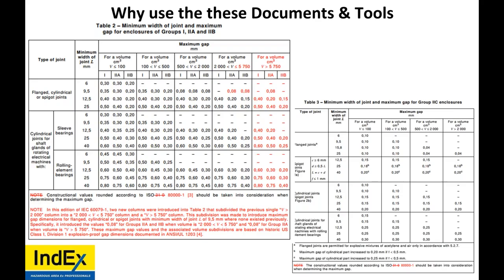If the equipment has an IECEx number for normal Ex, but also has a UL listing for its AEx, NEC 505 considerations, then yes, that can be used everywhere in the world, but you have to be careful. And as for mixing them, really not a good idea. They are tested, they are completely different. They're just both called Ex d, that's the problem.